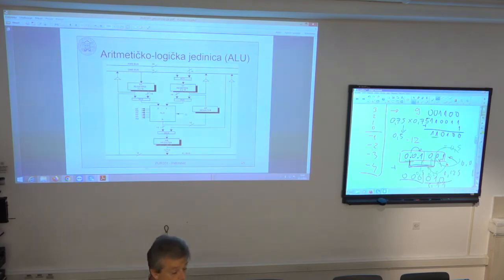And to speed this up, the idea is, why don't I use a temporary set of registers just for servicing the interrupt request routine. This temporary set of registers are these shadowing registers. I simply swap the main set of registers with the shadowing registers, do the desired interrupt service routine, and then swap back. This swapping is instantaneous. Only one cycle is sufficient to swap these two register banks. This mirroring is the fastest way to do the context store, but nevertheless, it cannot be nested.